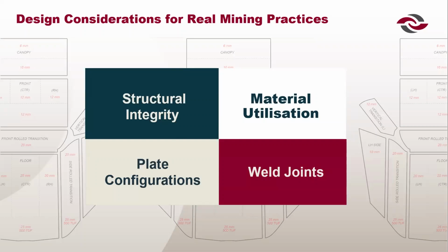Coming to the next point, material utilization is the next step, where we don't just use thicker steel. We use the right steel. Q&T plates balance strength and weight. In some areas, lighter plates reduce dead weight. In others, hardened liners extend wear life. It's about precision, not excess. Plate configuration is equally important. Plates are laid out to distribute stress evenly, reduce sharp transitions, and make replacements easier. This lowers maintenance time and extends the structural life.